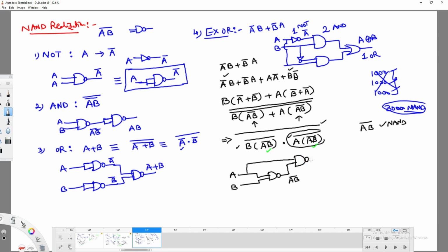A into AB complement we got. For that I am going to have once again a complement. Now this one acts as this one. Similarly, B into AB complement we got. For that the whole complement is a NAND gate. This expression is done, this expression is also done. For that you need to have again a whole complement, right? You know. That's it. This is the corresponding XOR gate, XOR gate in terms of NAND gate, right?